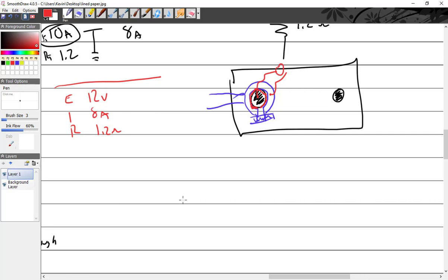Yeah. So you take an ohm meter and you go between the two. What should you see? Zero. There should be no resistance. And you do that, and the needle barely shows something, hardly anything, right? Huh, is that the problem?